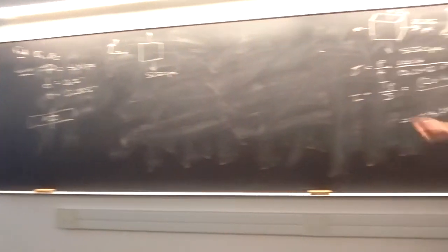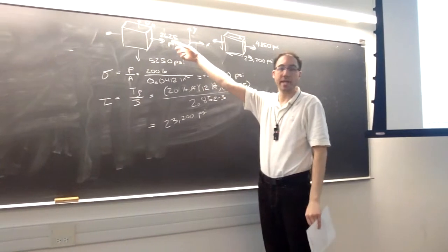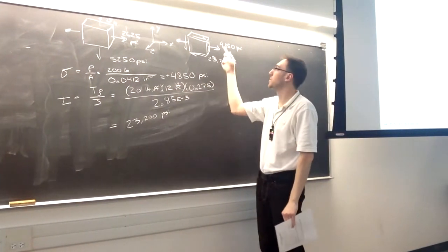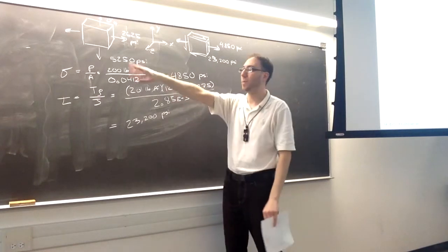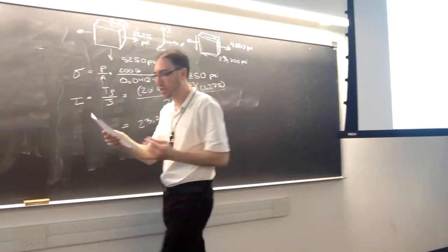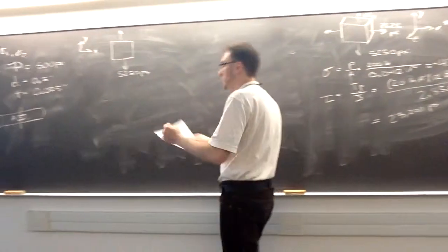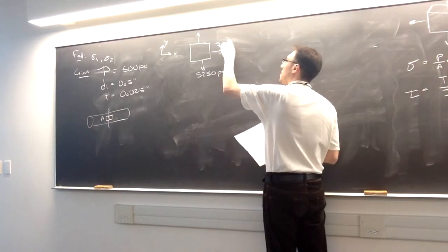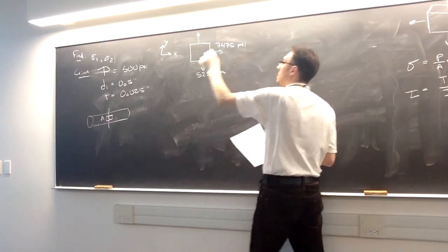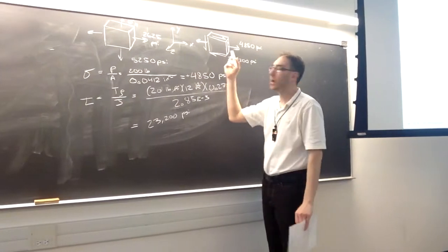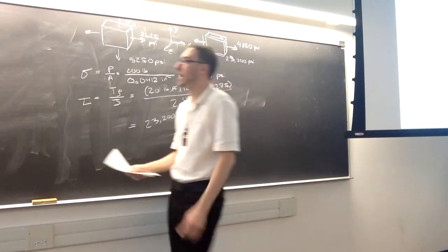On the X faces, though, I have stress due to the internal pressure, which is tensile, and stress due to the axial load, also tensile. So in my complete stress state, I have to add these 2 effects together to get the total stress in the X direction, 7475 psi. And between the 2 pictures I made, I only have 1 shear stress, so I can just copy that exactly.